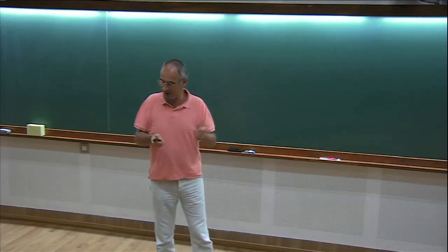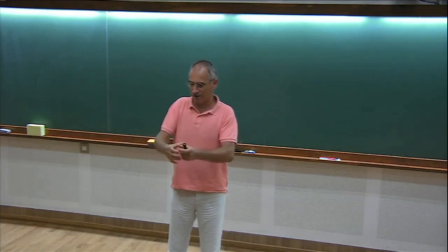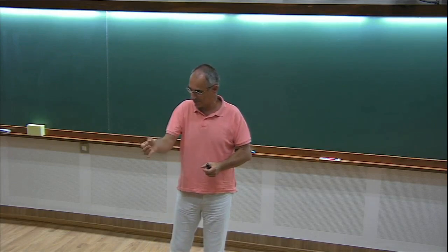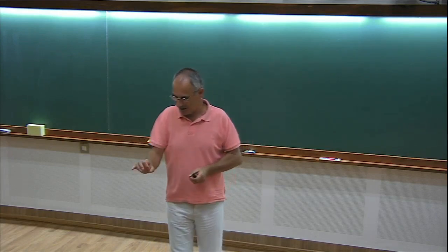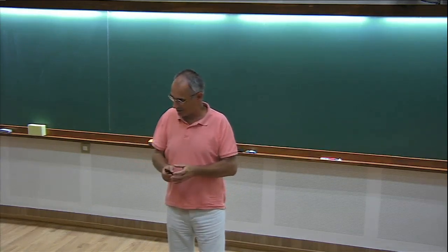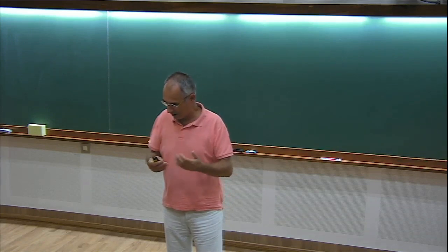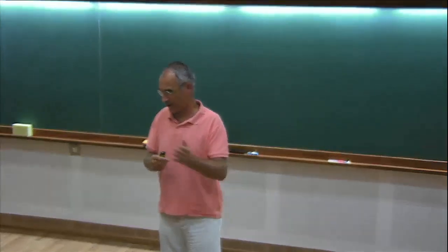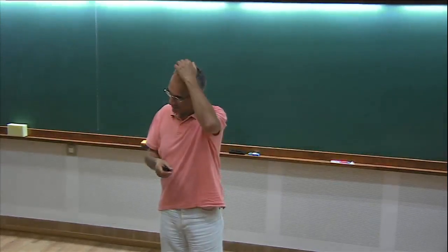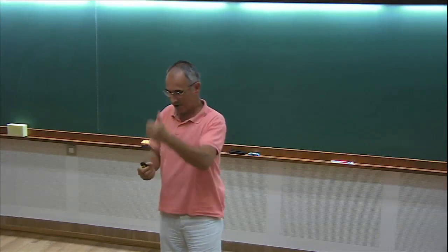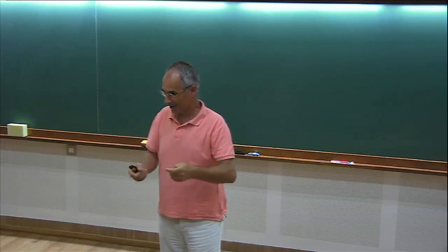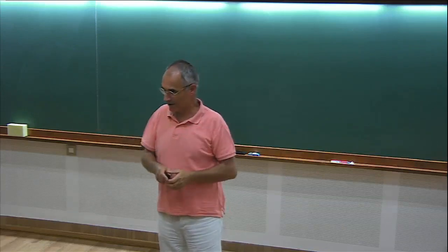Of course, you can get instability. So if you take a coin and you drill a hole in the center, you will get your coin, well, zigzagging or tumbling also. But you have to wait for larger inertia ratios or larger Reynolds number. So basically, it plays in favor of stability because it allows fluid to go through the center instead of having to go around the edge.